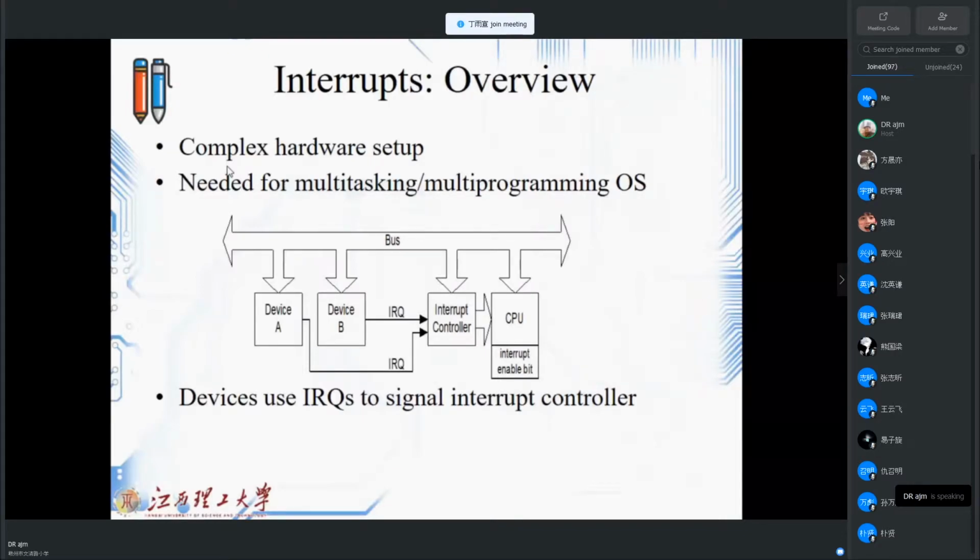Whenever anything happens to that, you can see that through the interrupt controller, the data will transfer to the CPU. Then what is the job of the interrupt controller? The interrupt controller should see which request or which IRQ has the priority, and also which one is activated first.